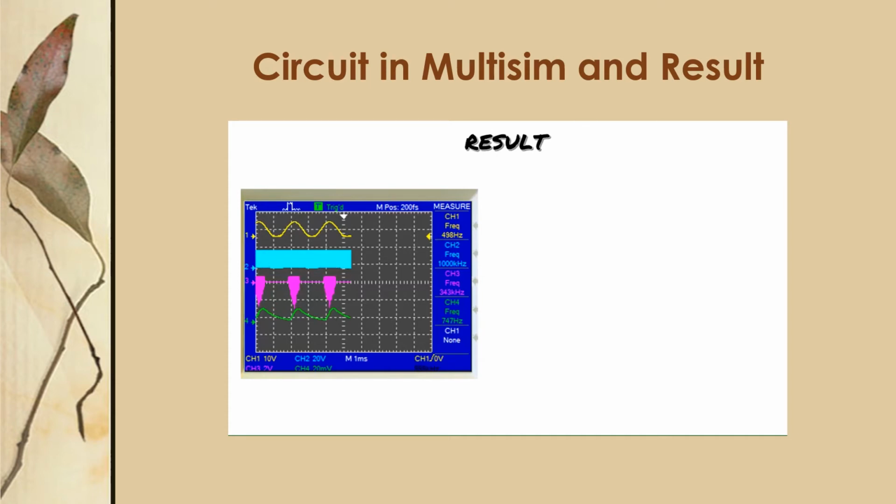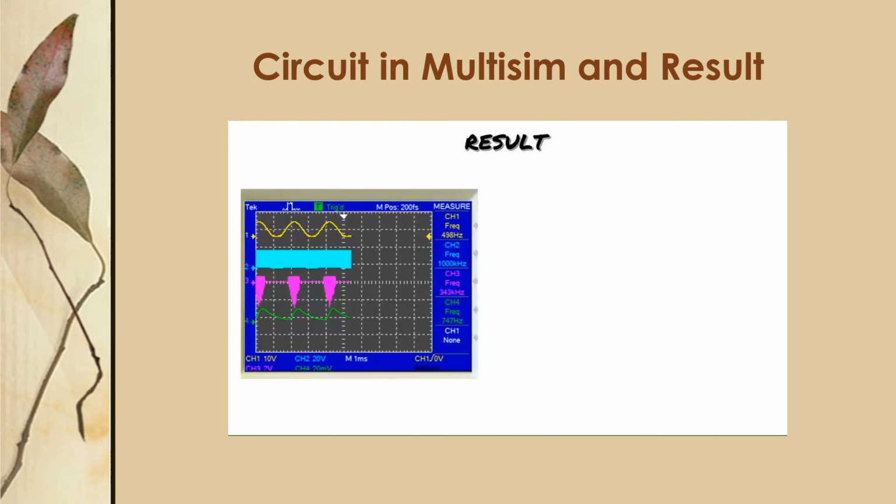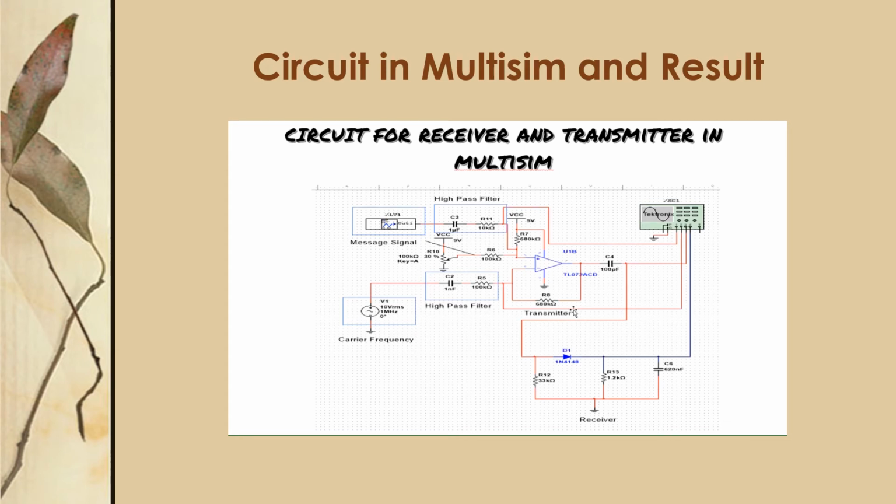For the modulation, this is what we get. Next, diode. This diode is a Schottky diode. That Schottky diode activates at 0.2 volt. Direct detector for receiver, direct detector is very simple, low cost, but it has a problem and is not sensitive.